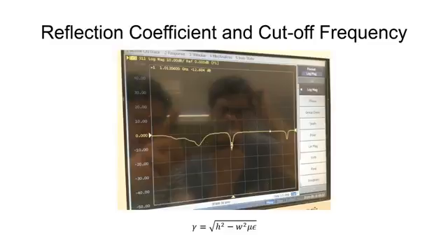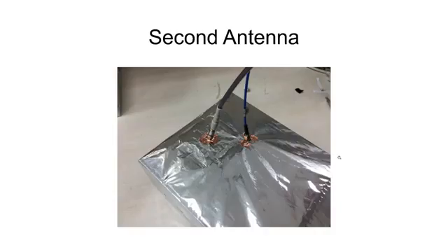In this range you can see it is like a normal line, because in that range gamma is imaginary, so there is no attenuation. This is the area that we want to work in. There is also a drop in here. This is for the other modes of the cavity resonator.